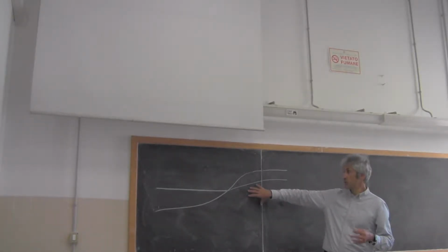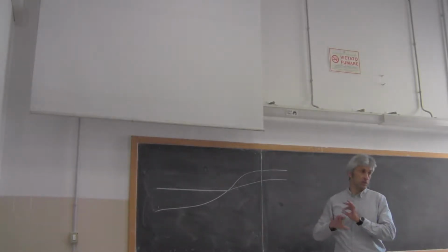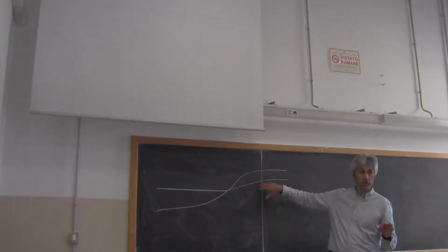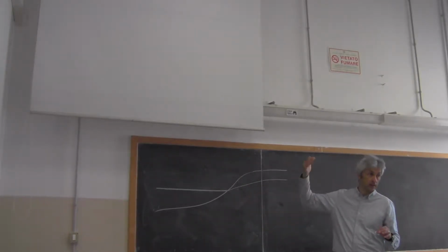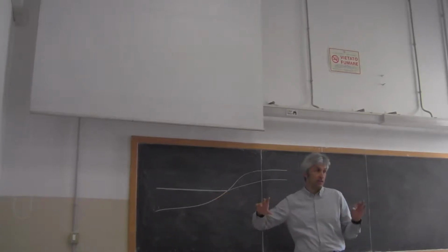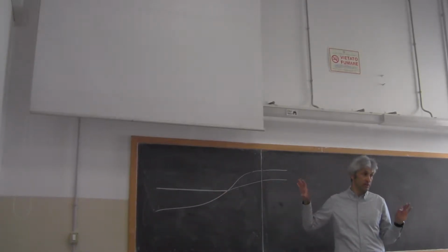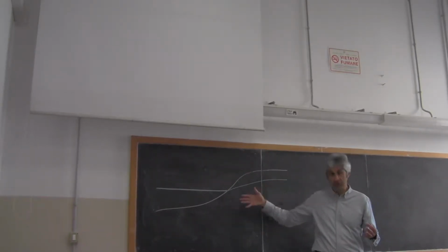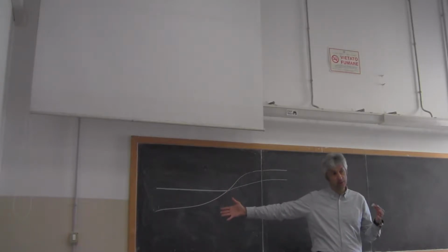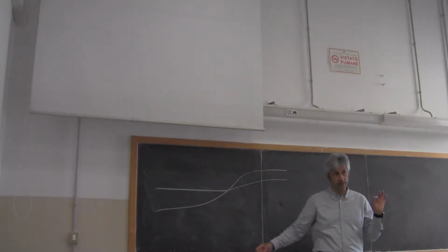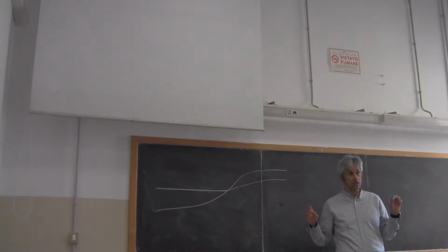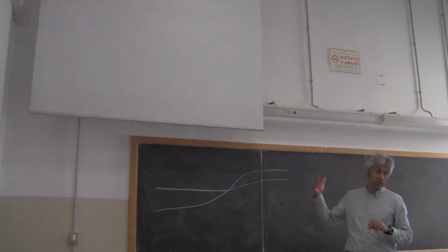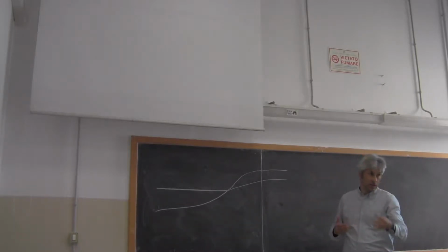Because with a situation like this, it's clear that you don't have any saltwater intrusion. When you have the freshwater table at such a high elevation with respect to the sea level, the freshwater flow dominates. In such a situation, you have a flow of fresh water into the ocean rather than the opposite. We will have the opportunity to check this in the exercise that I will propose to you shortly. But in order to be clear, I need to exaggerate the scale a little bit.